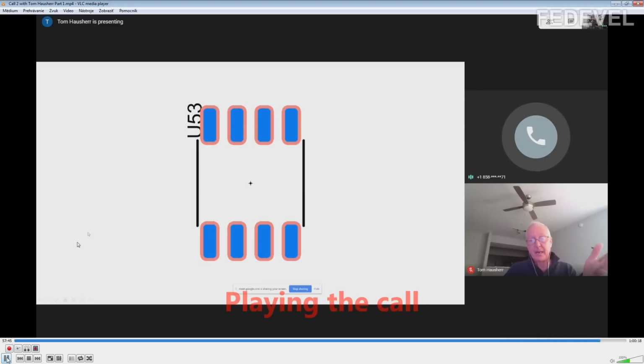Okay, now we're talking about solder mask, and we're talking about legend, silkscreen legend. The reason why we don't call it really silkscreen anymore is because silkscreen is a process. Silkscreen is like a physical process where you have a screen and you have some paint and you have a squeegee and you squeegee the ink onto the screen, and that's called silkscreening. The actual name of these markings, which they now apply on the printed circuit board using an inkjet printer, is called legend.